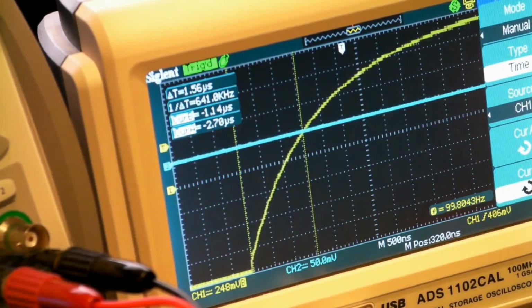It has a 13 picofarad load on the actual input of the oscilloscope, and then you have an additional 2 or 3 maybe picofarads on the actual probe tip as well. So these effectively end up being in parallel, giving you about 15 or 16 picofarads loading on your signal. So even though I don't have a capacitor in here at all right now, my square wave is already being put through an RC network and causing this curve where we can now measure. And what we'll do in a moment when we start doing the calculations is we'll actually verify the input capacitance of the oscilloscope with these probes that I've got.